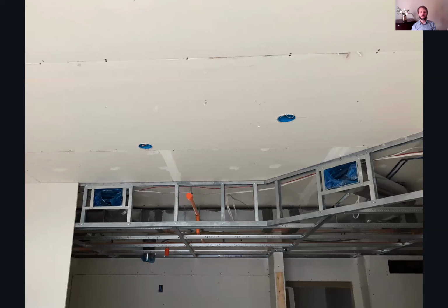During construction, you want to make sure that your ducts are covered really well. You can see here, if you look real closely, some blue plastic up, making sure that dust and dirt isn't getting pulled into the ducts and then sucked into the HVAC system. We just had a project where our rater was on site telling us about how this never happened. And so now the filters are super dirty and they're kicking out some nasty air through the HVAC, and it reduces the life of the HVAC system. So again, you want to make sure these things are in place, and you want to make sure when construction is done that the ducts are cleaned out if there are ducts, and that the filters are changed as well.